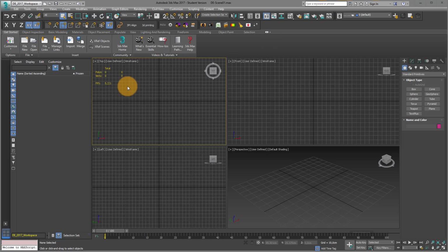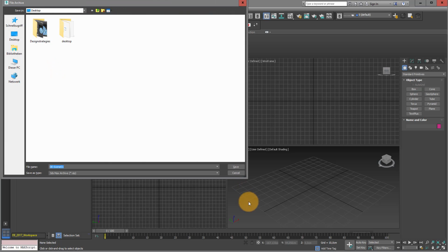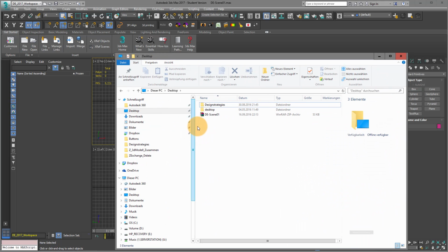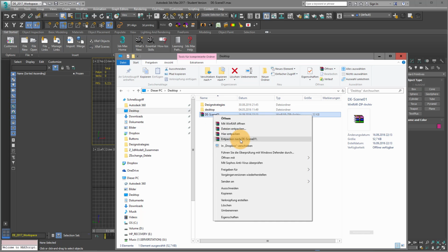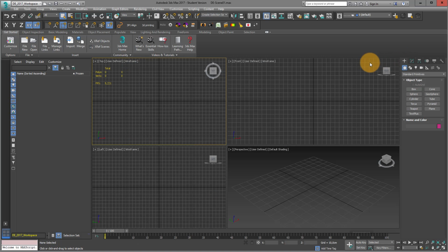These buttons under Get Started are a little bit like the buttons under the 3D Studio Max folder. Under File, Save, there's this Archive, which is a really interesting tool because normally all files like materials and textures are not integrated in 3D Studio Max. There are external files, and if you want to save them at one location, you should save it as a zip archive file. That's the best way of exchanging 3D Studio files and to be sure that all your objects and all your materials are a part of this.